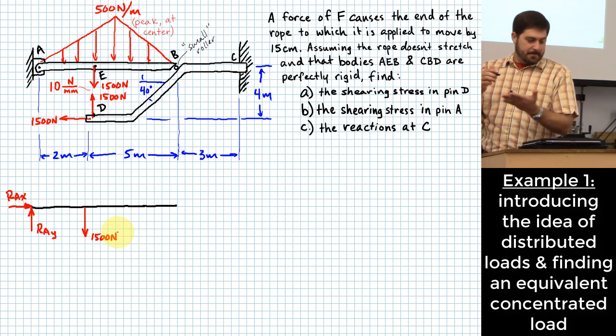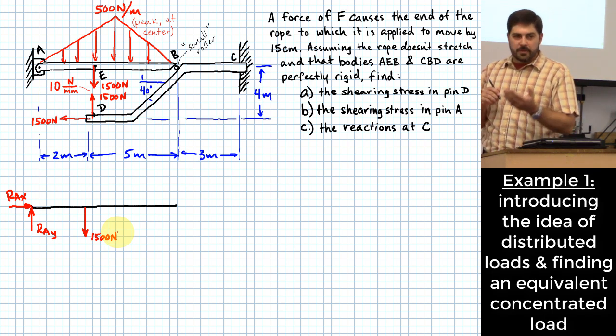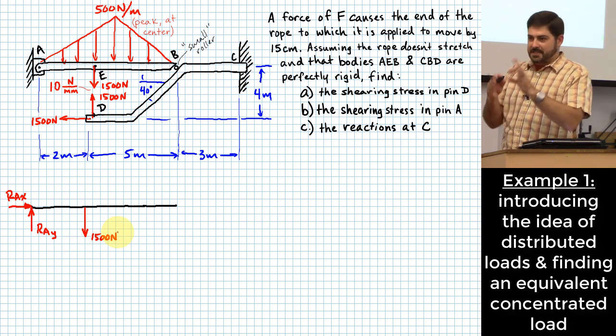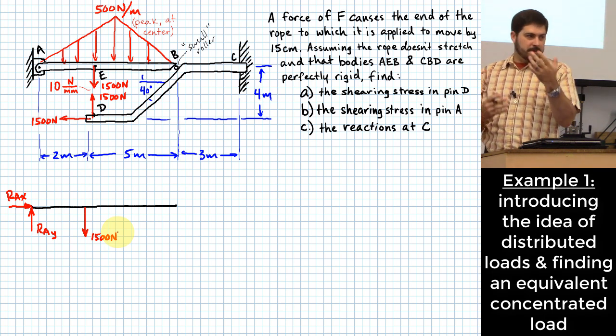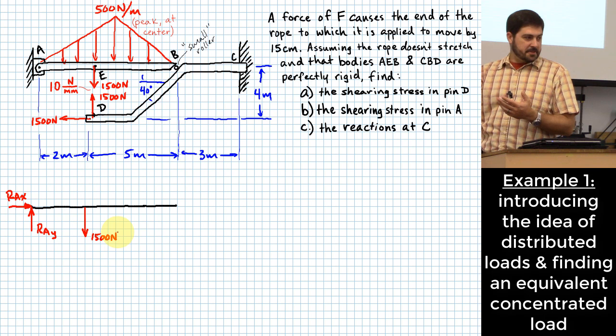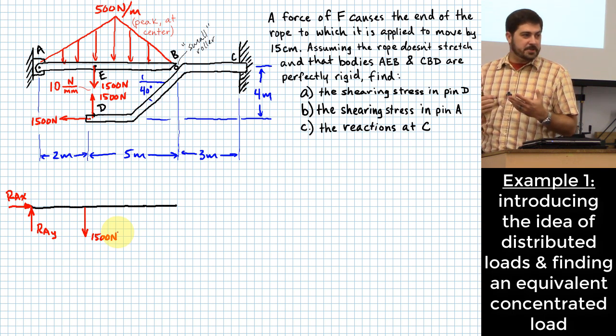Does that make sense? Well, what would that do to stress? Stress is force over area. The size of that thing is going to zero, so the area is going to zero, and force over zero area would be infinite stress, right? And materials can't carry infinite stress. There is no material that can carry an infinite stress.